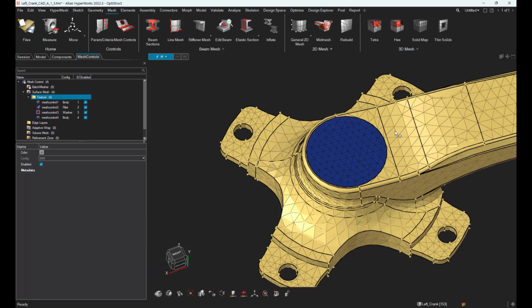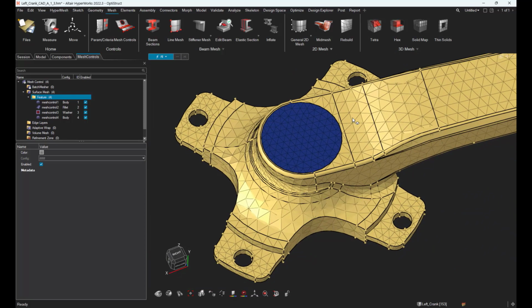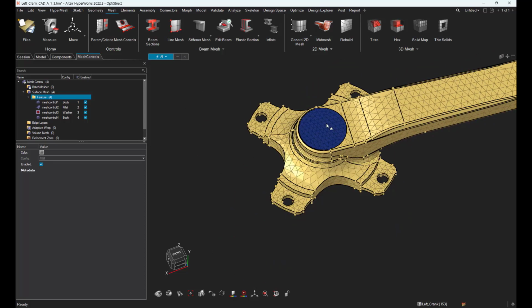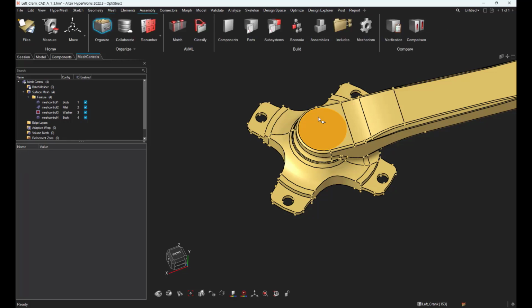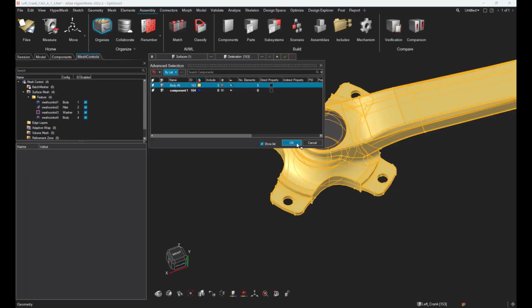So if you're in that case and would like to have a connected mesh between several components or parts, what you have to do is basically, let me delete every element, is basically to organize all your surfaces or solids into one comp, like that.